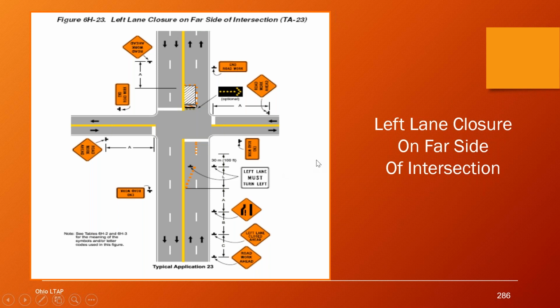If we looked at the notes page on this, there would actually be a discussion on whether or not you need that pocket created. That's why it's important to not only look at the drawing of the typical application, but read the notes page as well. When you're dealing with a multiple lane arterial intersection, this is not a boilerplate for every intersection.